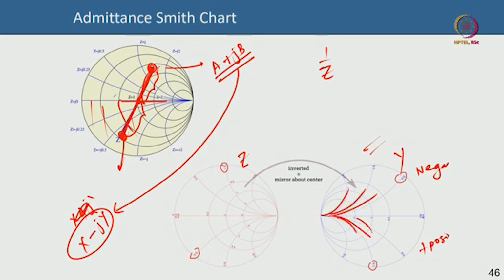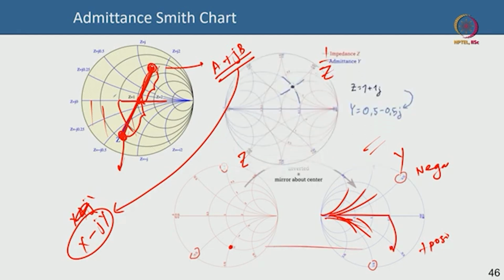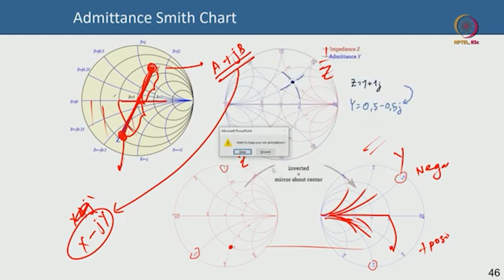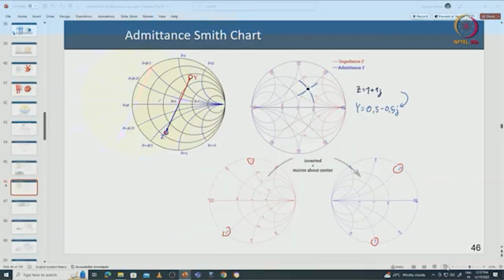See, it's exactly. Now if I have a point in the Smith chart, suppose here the original Smith chart, if I combine these two Smith charts again, I just look at this point here maybe, and I can read off this value here and I will get the admittance value, the equivalent admittance value. So what I mean is that, maybe I will remove the annotation, it will become very clear. It is actually very simple here.